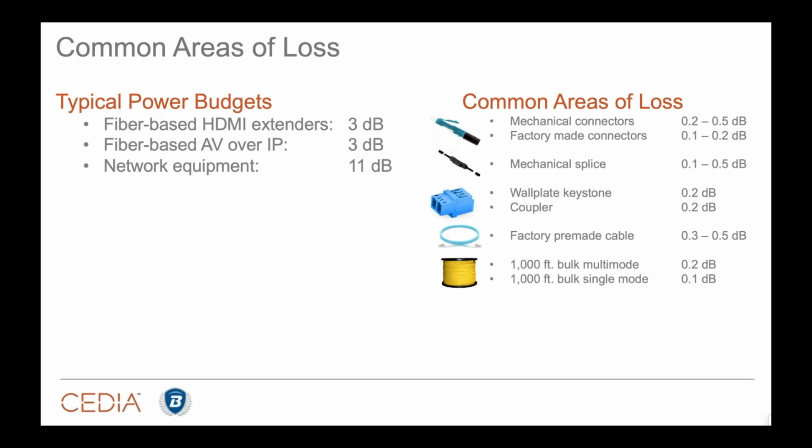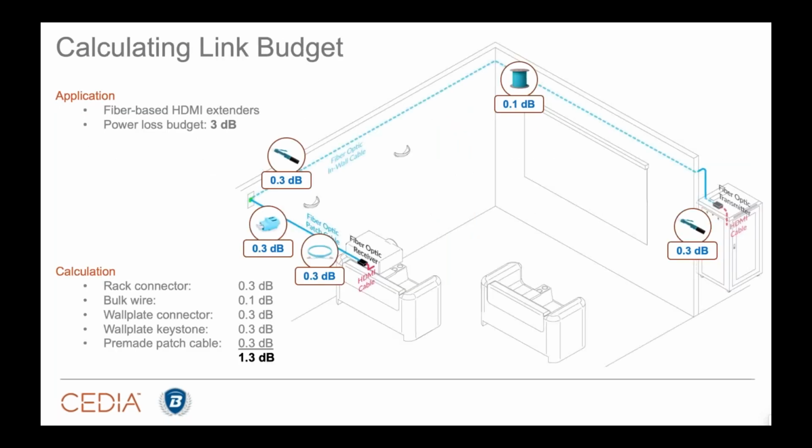So where does the loss come from? It's actually not the fiber optic cabling itself. We see that the glass and the polymers used in modern fiber construction are really good at what they do. They're really high quality. They're really pure. Those lasers transmit very cleanly through the cable. It's actually the splice points, the connectors, the couplers. That is where we're seeing our loss.